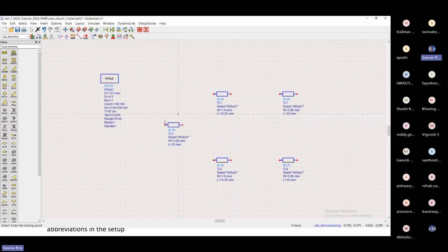So now what is required? Let's say we just make a simple line connector. See this here on the top bar, you see all the different options are available. I am taking from there. There you can define a variable, ground, port, and then you have the insert wire. This wire I am using. And there are other simulation options, tuning option, optimization option, lots of options available on the top palette.